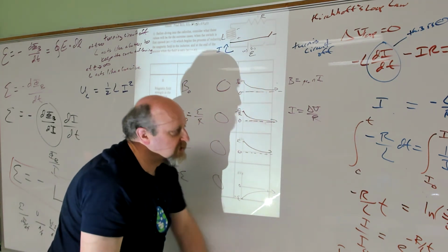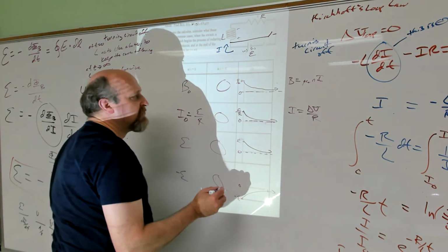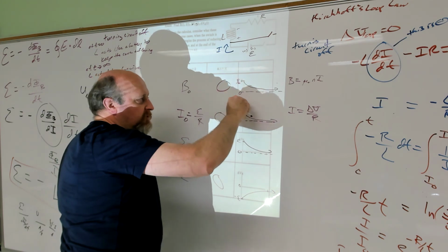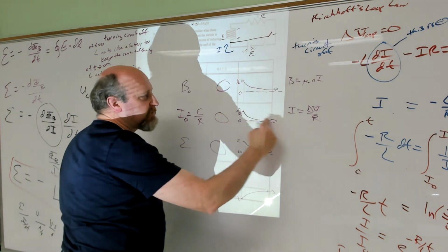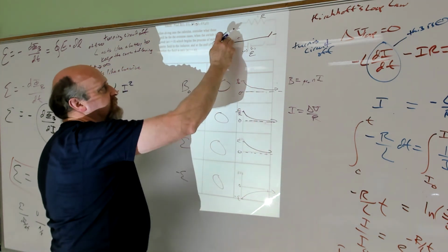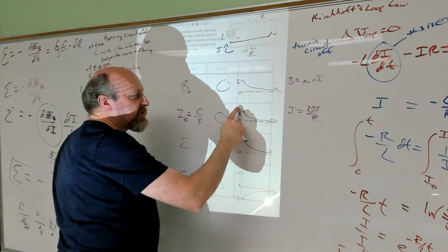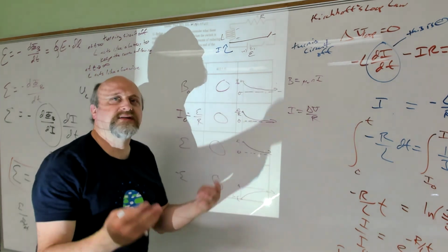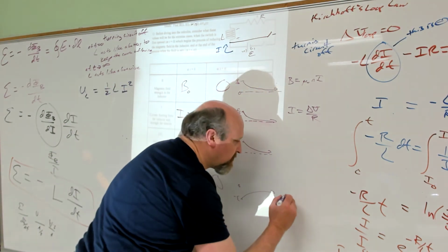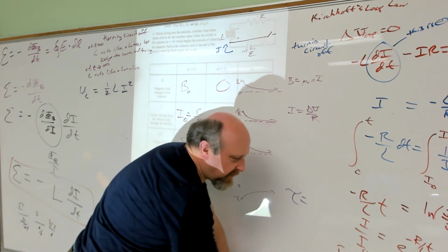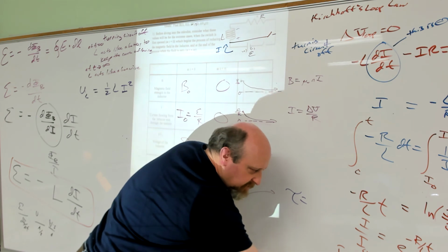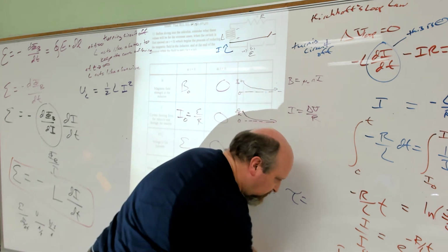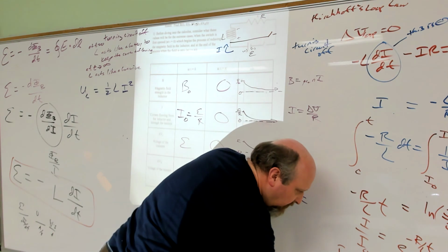Okay, perfect. So this is like the percentage that you're at. Hey, I can imagine having circuits that would drop more steeply than this one or drop more shallowly. All of them will take an infinite amount of time to totally drain the energy in that inductor. You say, but I can talk about how quickly they're dropping. How do I compare that with a time constant, tau? What's tau? It's the value for t that simplifies that exponent, makes that exponent negative 1. That exponent, again, is negative R over L times t.